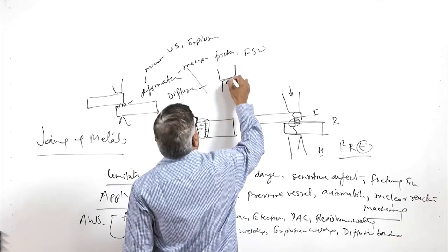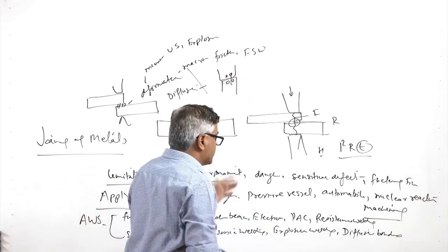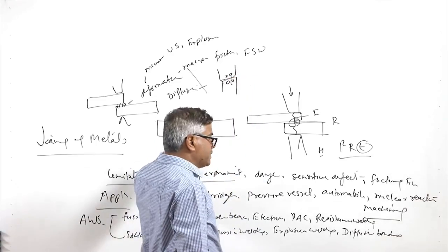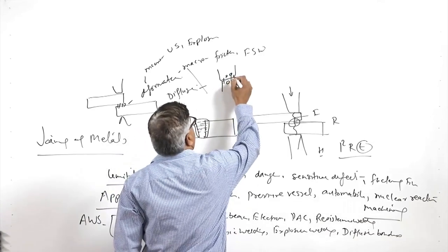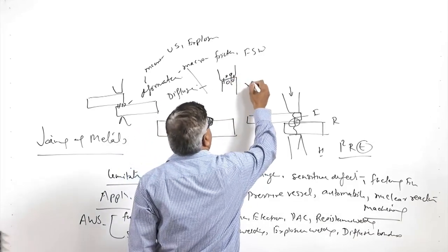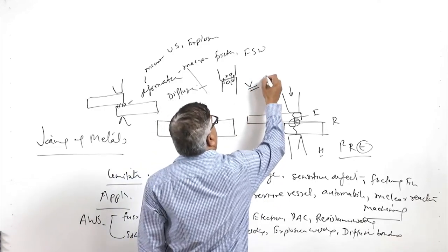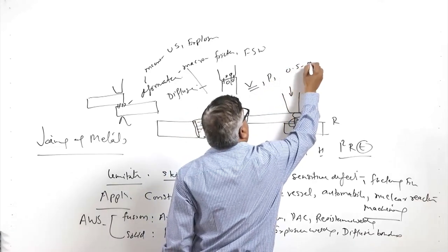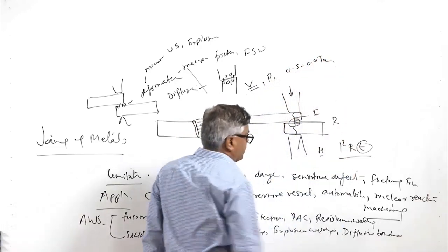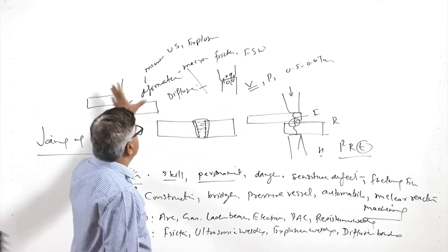So, diffusion of atoms from one side to another is facilitated due to the concentration gradient of the alloying elements, and the metallic continuity is established at a high temperature. Mostly this is conducted in vacuum and under pressure at a high temperature, like 0.5 to 0.6 times the melting point of the metals involved.